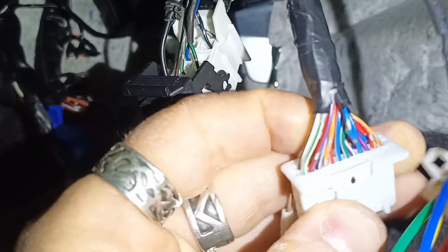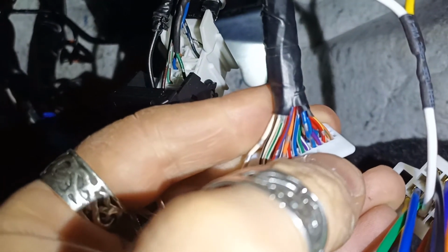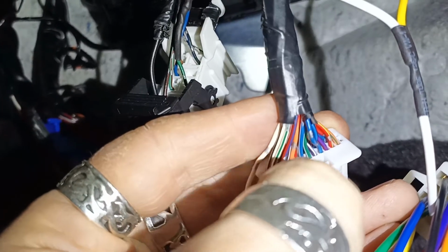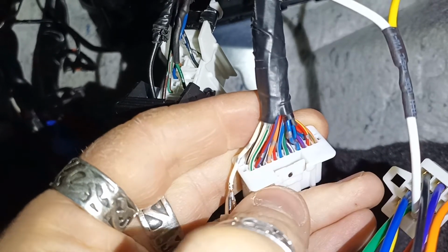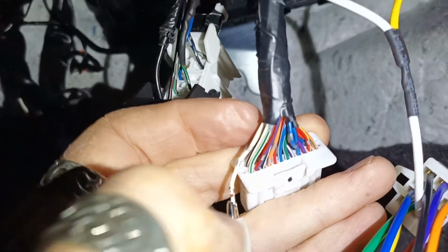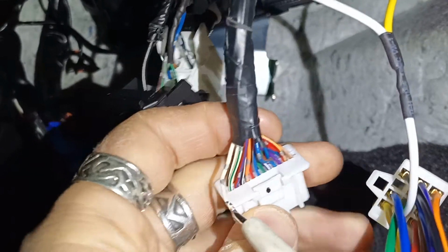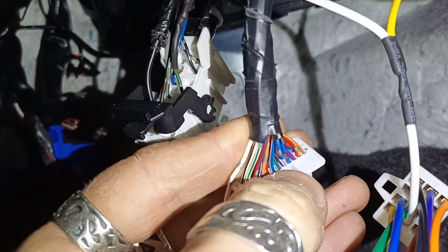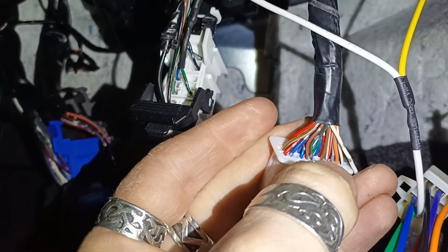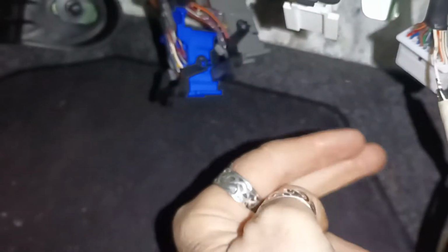Then from the other side, if you turn it around, there is barely visible violet with white. This is the most hidden one out of the whole row, violet with white. If we count looking at it like that from the right again, 1, 2, 3, 4, 5. So again, 5th from both sides when looking at the connector. This is for the low beams. Pass ground here and low beams will activate. Pass ground to this one and TNS is going to get activated. So this covers those 2.